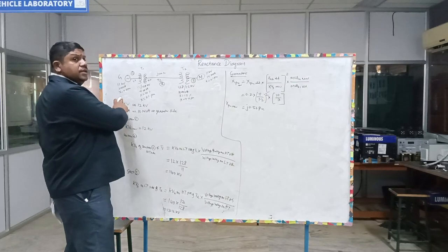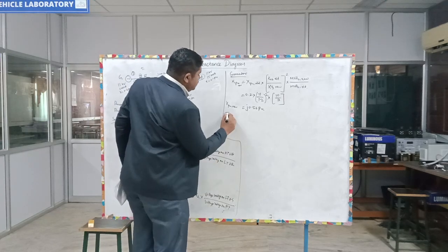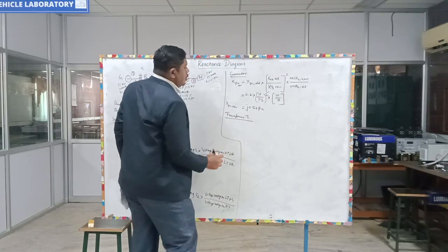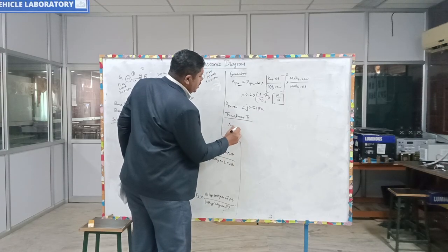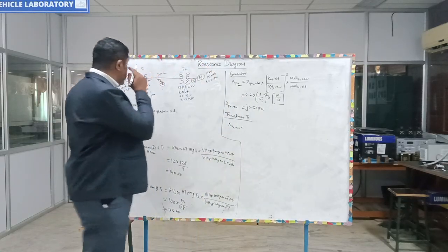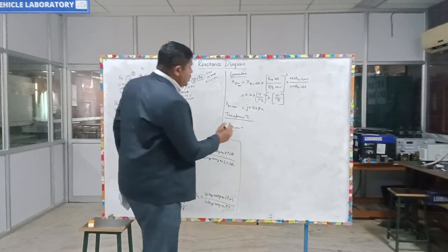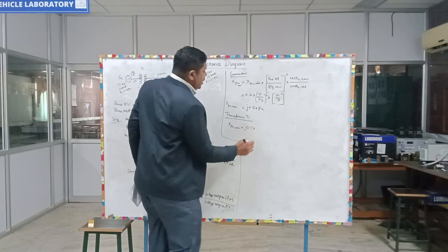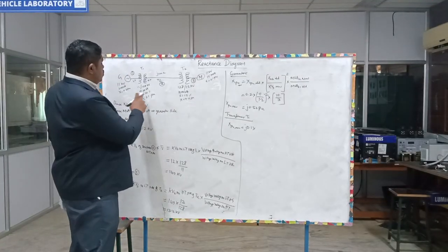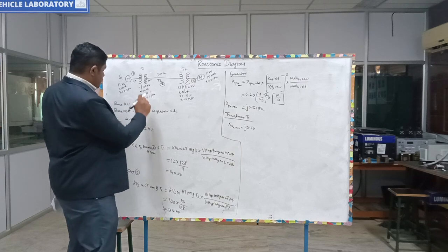So next you have to calculate for the transformer. We have calculated the reactance for the generator. Now you have to calculate it for transformer T1. What is the X per unit new? The formula is the same. X per unit old of transformer T1 is given in the problem. So it is j0.1 into kV base old by kV base new. The kV base old is here.